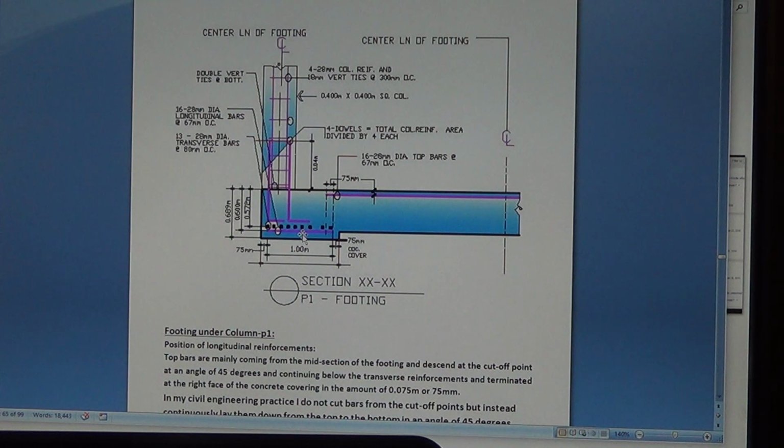See here, this is the bottom reinforcement, longitudinal reinforcement. This is in the long direction, and the transverse direction, don't make a mistake here, transverse direction is always on top of the longitudinal direction. Okay, to solve for this length here, where to place all this transverse reinforcement, there's a theory for that to get this 1 meter, and it's another long calculation there.